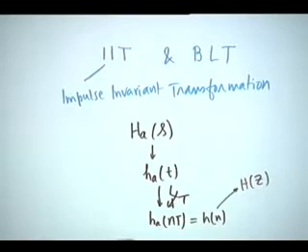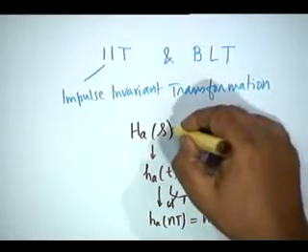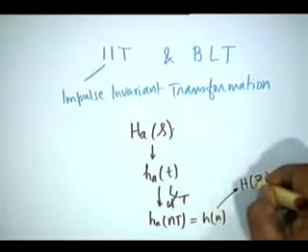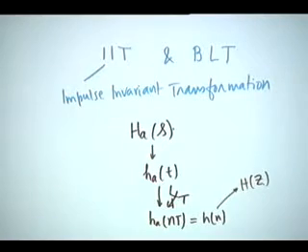So, the relationship between the analog filter and the digital filter: we have derived H(z) from H_a(s). The distinctive characteristic is that the impulse response remains invariant.